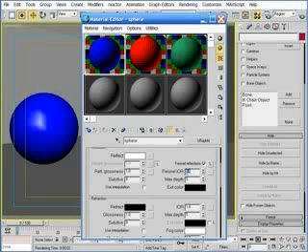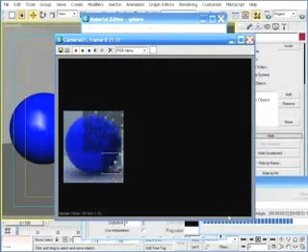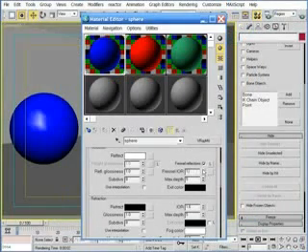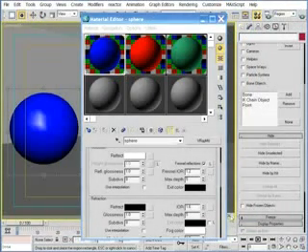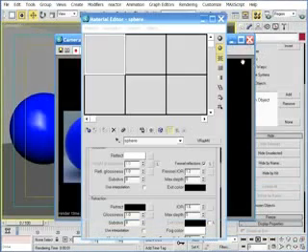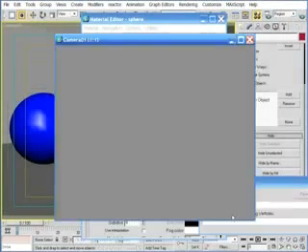When unlocked, you see a new index of refraction value enabled, and now Fresnel reflections are controlled right here. So to change the strength of the Fresnel effect, all I need to do is change this value. If I reduce the value, you can see that the strength of reflections everywhere is reduced. In fact, I can keep reducing it to the point that only reflections along the edge of the sphere are visible. Finally, if I reach a value of 1.0, there's no more reflections at all.